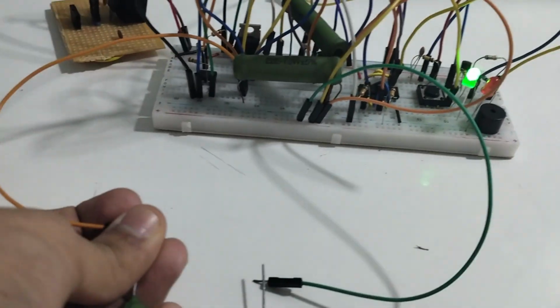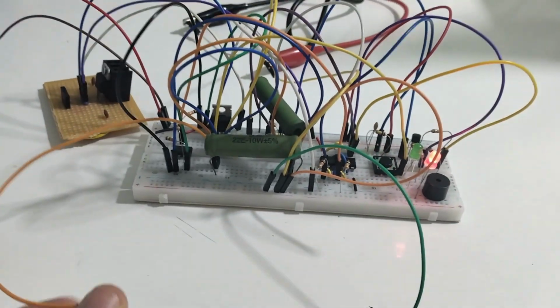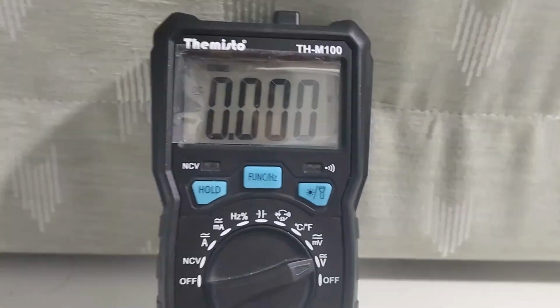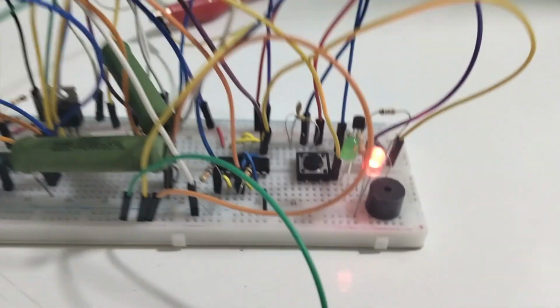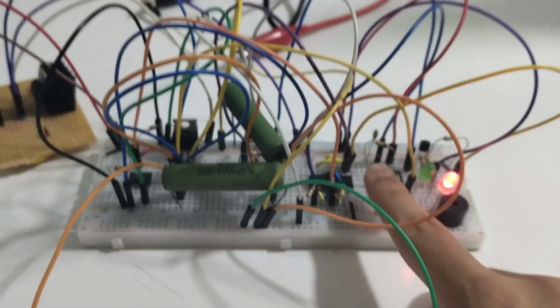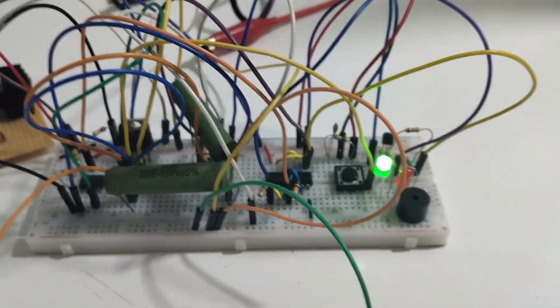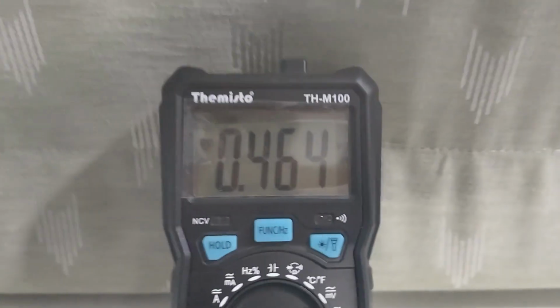And now I'll switch to the 10 ohm load, and you'll see how it triggers. Now I'm holding the 10 ohm in my hand, and now I'll just touch it with this, and you can see that the overcurrent has triggered, and the voltage across the shunt has dropped to 0 volts. So basically the current has been cut off, and you can see the red LED and the buzzer are sounding. To reset it, we have the reset switch, and that has turned off, and now it's back to normal operation, and the 460 milliamps has begun to flow again.